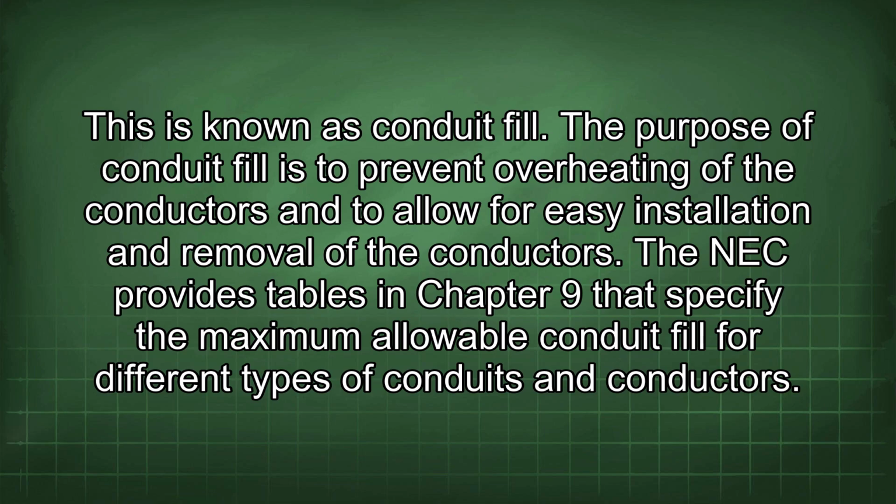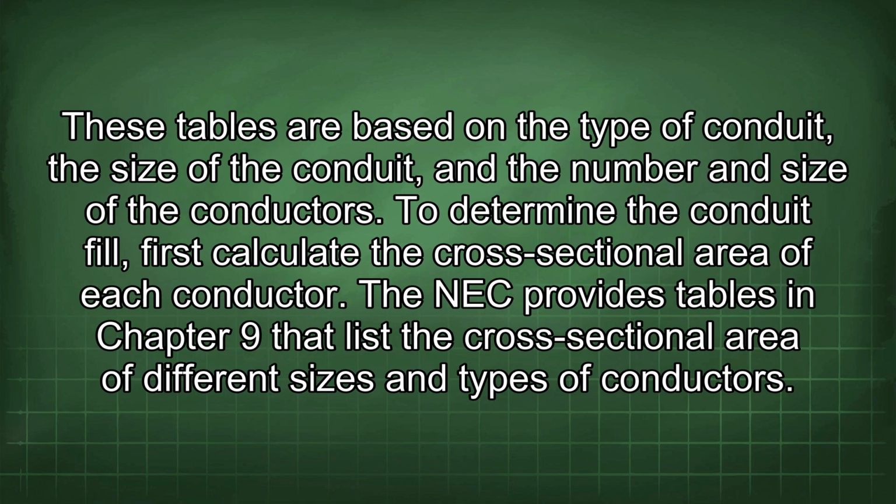The purpose of conduit fill is to prevent overheating of the conductors and to allow for easy installation and removal of the conductors. The NEC provides tables in Chapter 9 that specify the maximum allowable conduit fill for different types of conduits and conductors. These tables are based on the type of conduit, the size of the conduit, and the number and size of the conductors.